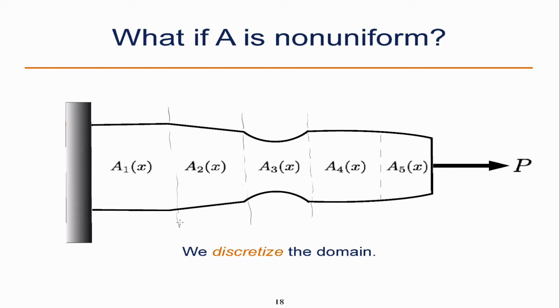So these are all things we know. We have analytic solutions, and we can write them down. Therefore, we can use the principle of continuity and superposition. Continuity would only mean that in the solution across this distance, I just have to make sure my boundary conditions are consistent, such that the displacement at this point is continuous. It has to be the same as the displacement there and there, right? So when I solve all these, I need to ensure that my boundary conditions are correct. But then I can use those known solutions, okay?